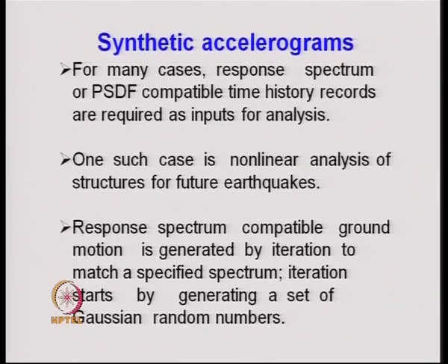Next we come to the synthetic accelerograms. For many cases one may have to obtain response spectrum or power spectral density function which are compatible with the time history records, or for a given response spectrum or a given power spectral density function one may have to calculate synthetically a compatible time history record.